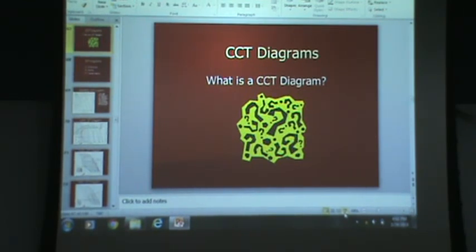And the concern is that in this region here and here, the mass is, you know, say a 20-inch diameter ball in there, but the web here, which of course I didn't draw very uniformly, the web is only about 7 inches. So that grade doesn't undergo a phase transformation for quenching, but it does have the thermal expansion and contraction issues.